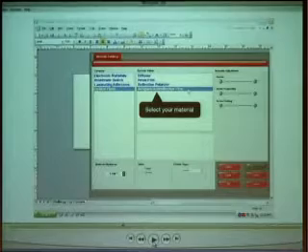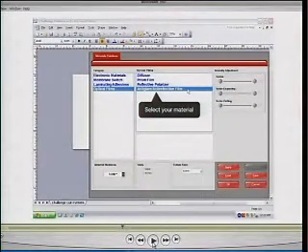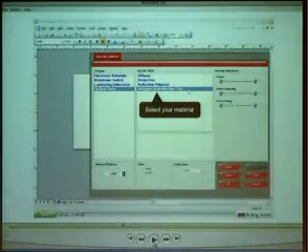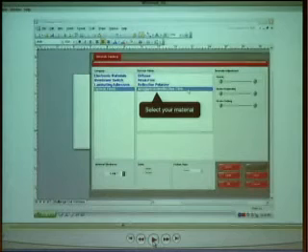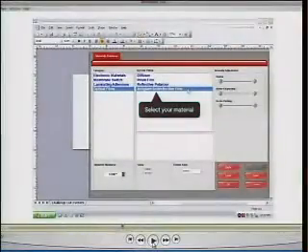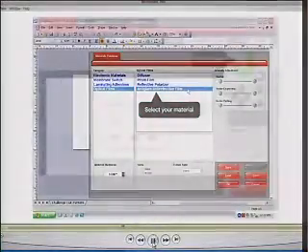The full materials database would have plastics and metals, etc. But if we select optical films, diffusers come up, prism films, reflective polarizer, and then the one we selected here is the anti-glare, anti-reflective film from the front side of the stack. Enter the thickness here, which is 10 thousandths, and then press OK.